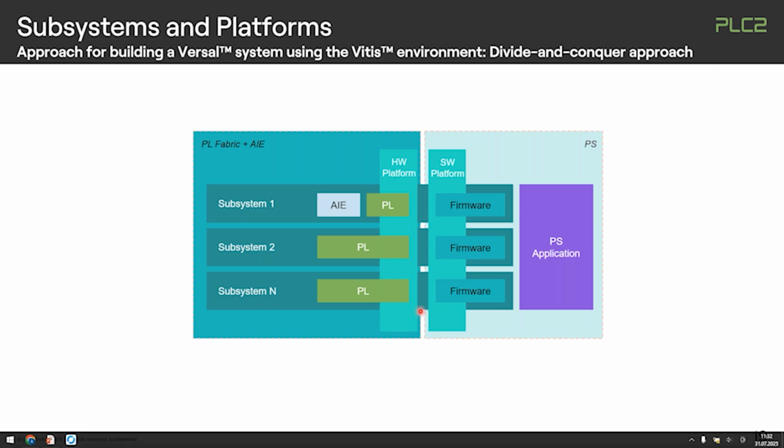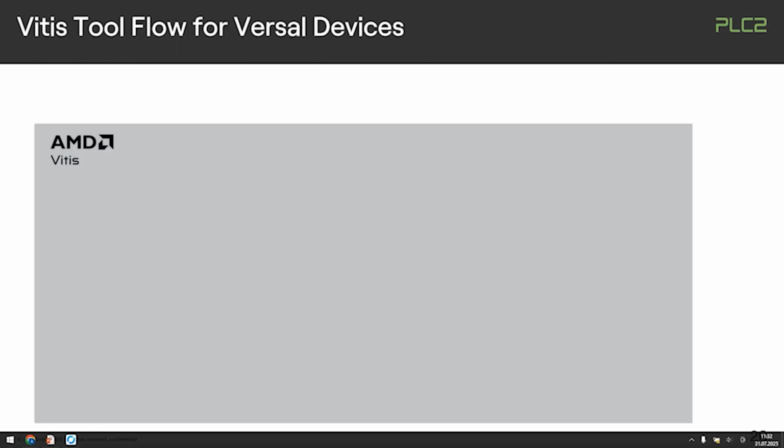Then on the other hand, we have the hardware platform, and that really means that you need to provide this address map in the first place at one point. Now that can be created out of what we saw before, the Vivado tool flow that has this block diagram and everything is nicely written up and nicely connected there. But it can also be assembled in software-defined projects, and that's what we will have to look at in the next step. So when you look into these three different compute domains, like the vectorized compute, the arbitrary flexible compute on PL, and the PS compute, all of them will come with